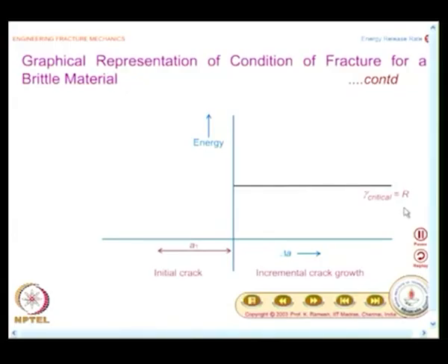But if you want to generalize it, it is rather wise to look at it in terms of G and R. R is supposed to be an inherent property of the material, and for the case of brittle material, R is linked to surface energy. When you say the surface energy, you tend to have that as constant, and we will develop another kind of graphical representation.